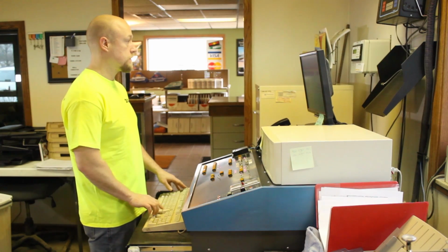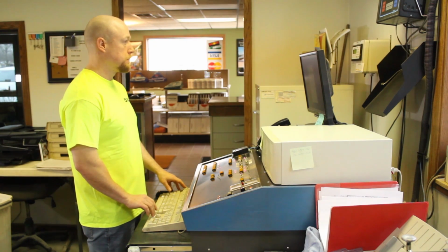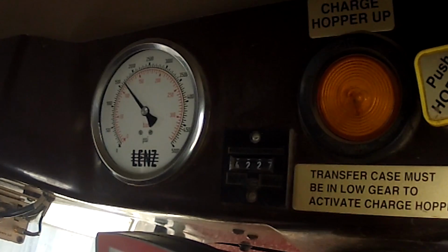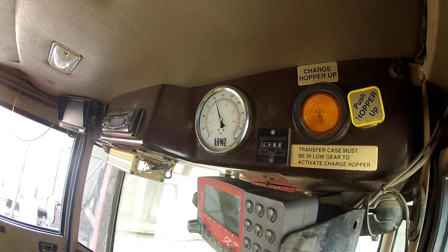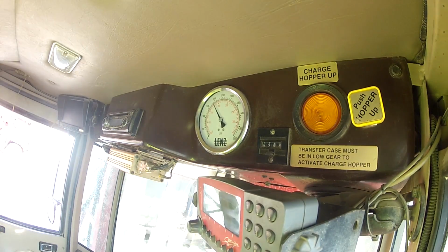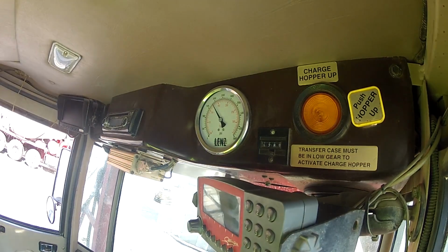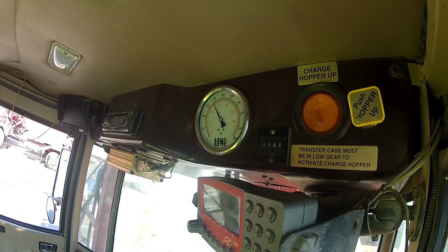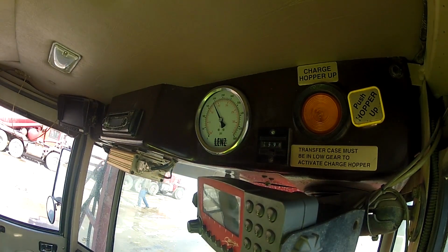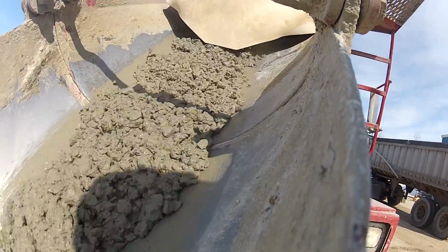Your plant manager will batch the concrete so that it is close to the desired slump, but it will be up to you to adjust it to its final consistency. Your chief tool to help you do this is the slump meter, but it is very important to visually inspect every load to make sure the slump meter is correct. The slump meter does not directly measure slump, but instead measures the hydraulic pressure it takes to turn the barrel and mix the concrete. This pressure is usually an accurate way to gauge the slump of the concrete.